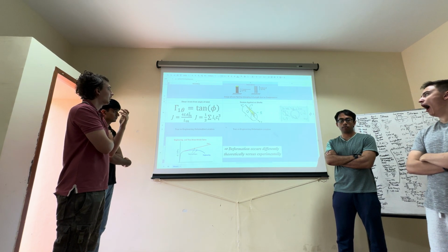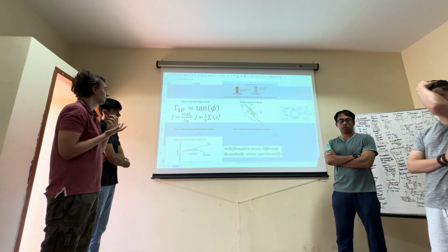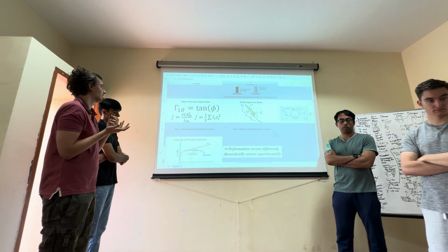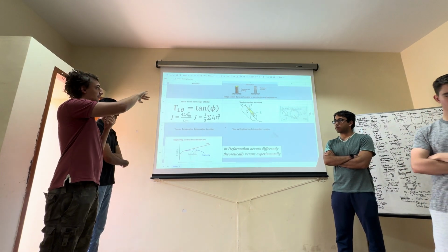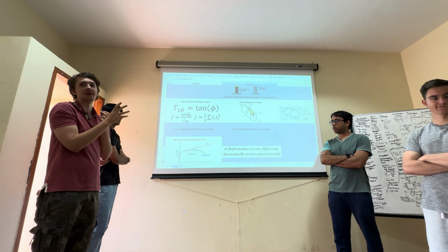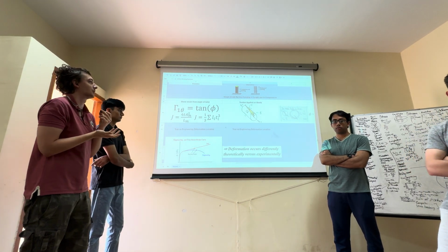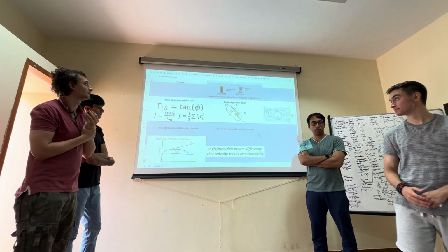First one being relevant for closed thin-walled cross-sections, and the second one being for open cross-sections. Basically, you sum up the length of the cross-section and then multiply it by thickness to get the cross-sectional area of the object.